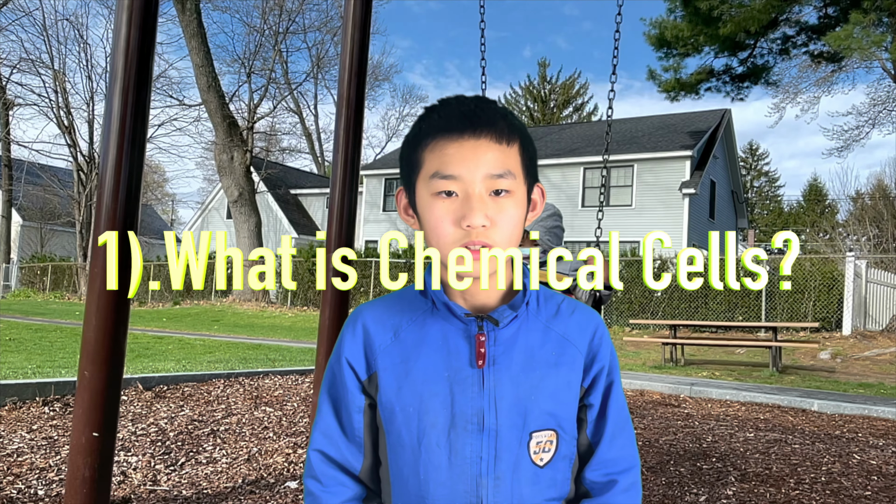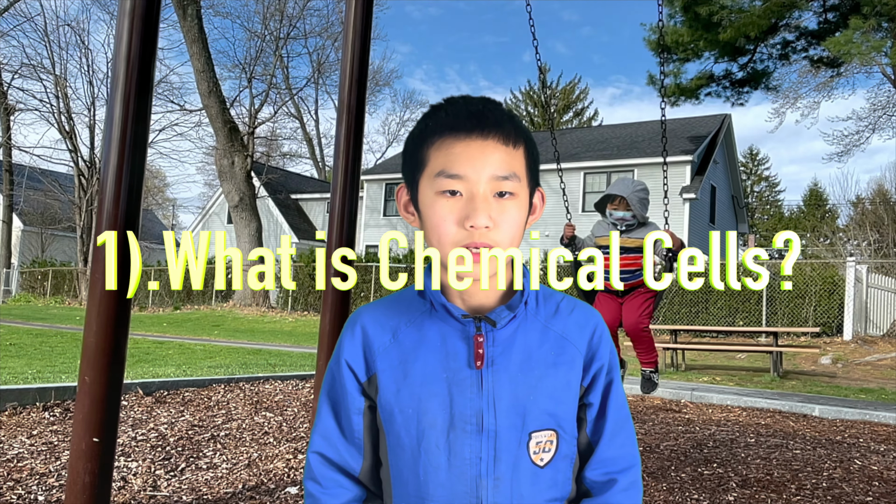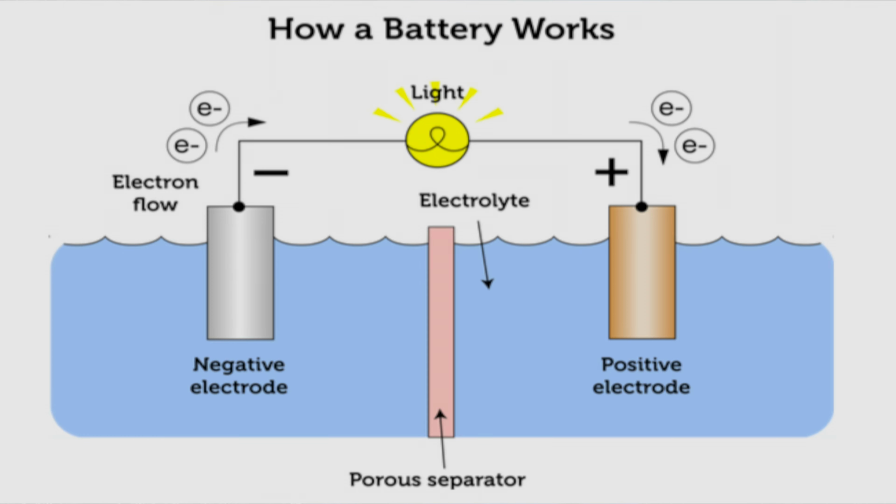What are chemical cells? Chemical cells are found in batteries. They produce voltage by means of chemical reactions. Chemical cells have two electrodes, which are strips made of different materials, such as zinc and carbon. The simplest type of battery contains a single cell. Electrodes extend out of the battery for the attachment of wires that carry the current. Electrodes are suspended in an electrolyte. The electrolyte is a substance containing free ions that can carry electric current.